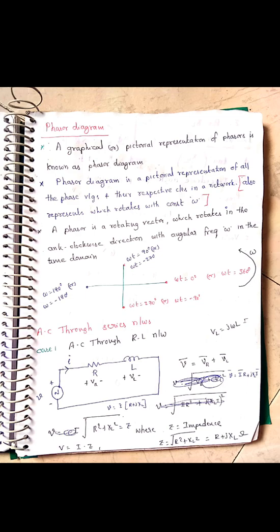If current flows through the resistor, according to Ohm's law voltage will exist, similarly across the inductor also. The voltage across the resistor is time invariant, while the voltage across the inductor is time variant. Why? Because it's frequency dependent, since omega is equal to 2 pi f. So the sum of these two passive elements requires a vector sum, meaning the J operator.